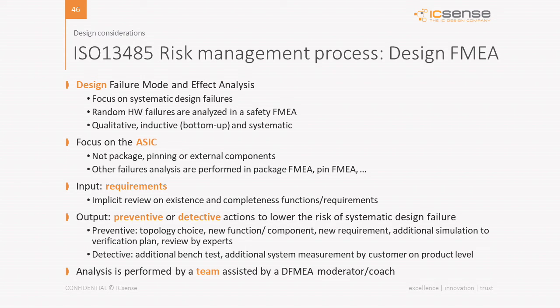Having a closer look at that, what do we do for that? As a design partner, we perform a specific design FMEA, design failure mode and effect analysis, where we focus on real systematic design failures. Random hardware failures are not part of the design FMEA, but are analyzed in a safety FMEA.